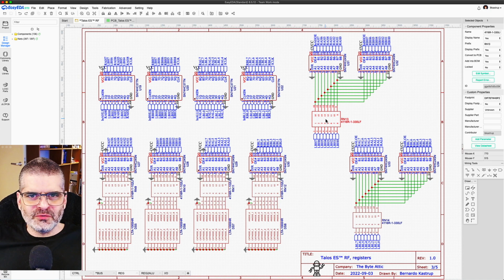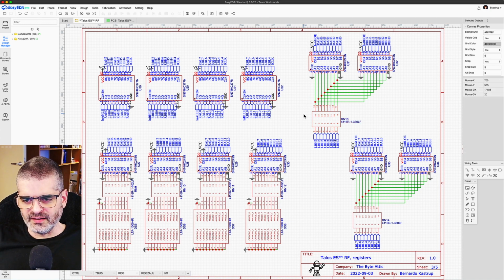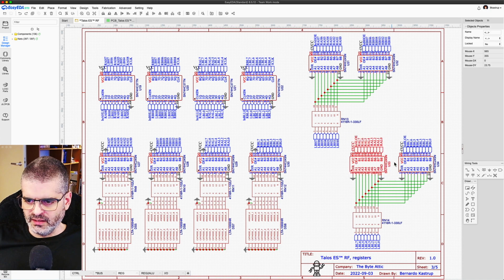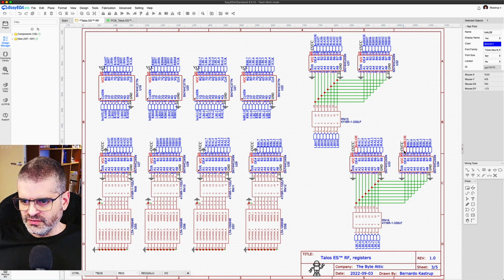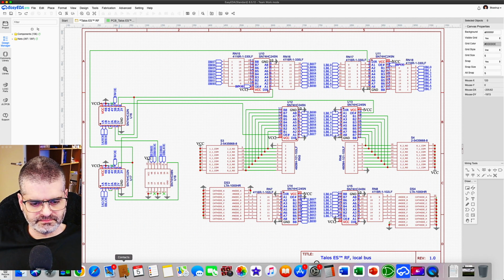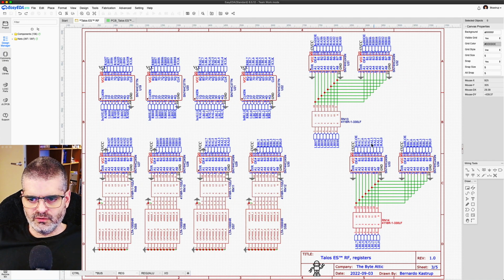So what tends to get reflected are the very high frequencies with very small wavelength, even at the speed of light. So we have to use a low-pass filter to eliminate the high stuff. And this is the same thing, but for the low byte of the bus, which can be driven by A low or B low, or none of them, depending on these control lines here. So that's the register page.